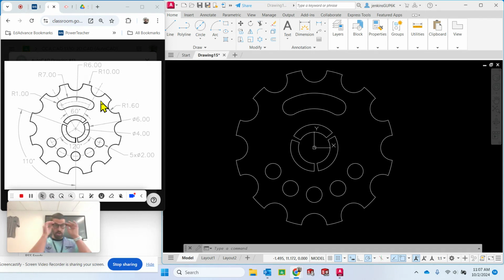You can control all the parameters of what you want to do with that polar array, but essentially the gist of it is that it allows you to take one element and repeat that element around a central rotating center point. So it's a really useful tool. There are other kinds of arrays which we'll talk about later on, but for today it's the polar array, P-O-L-A-R, like the pole, like the North Pole.